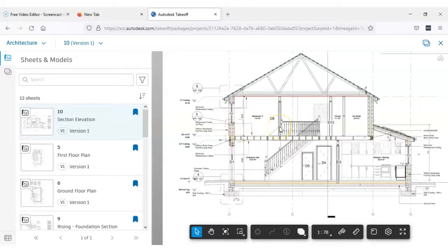So of course, as I said before, we don't measure off sections, we don't measure off elevations, we don't measure off details, or at least we try not to. We measure off plans. We measure everything off plans. Maybe if there's a window area we're looking for in a cost plan, possibly we can measure off the elevations.